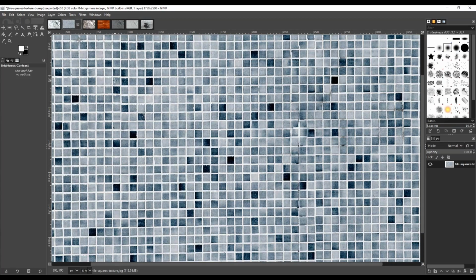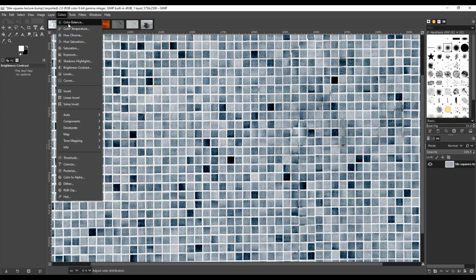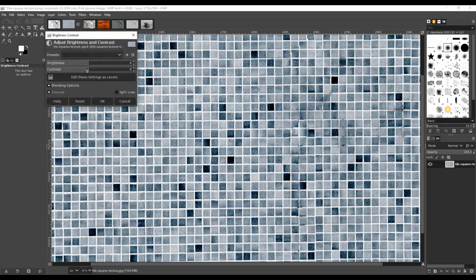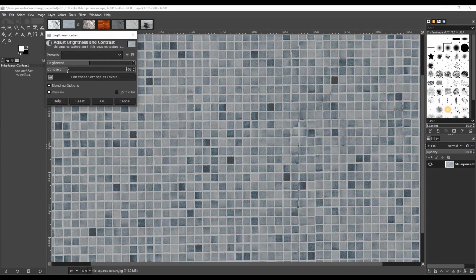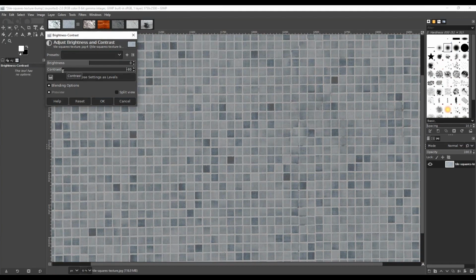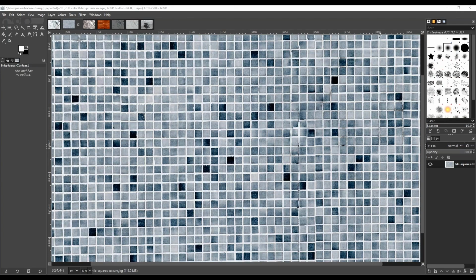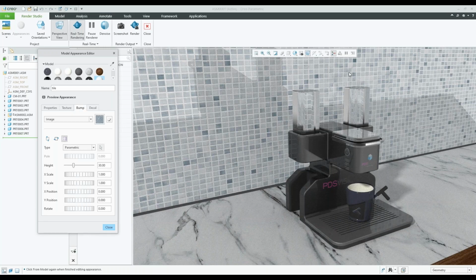So this is the high contrast one that gives the bump map for that sense of depth, but the original one didn't have as much contrast, so if I turn this down, the original one looked more like that. Okay, so it's important to note, and this is the reason why I'm showing that, if you want to get the illusion of depth for stuff like this, you want to use both a bump map here and a texture map.